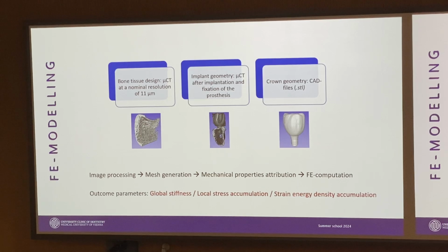The model was transferred into a network of tetrahedral elements with defined mechanical properties for each simulated material. Models were assumed to be isotropic, homogeneous, and linearly elastic, and the outcome parameters included global stiffness, local stress accumulation, and strain energy density accumulation.